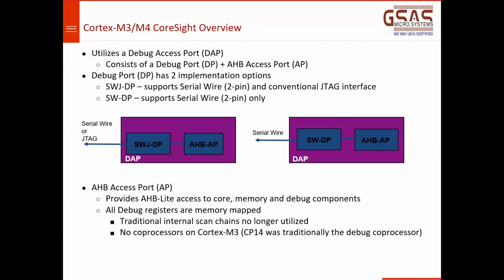And how can you access them through this access port? Using this AHB-Lite bus, which is again connected to the AHB bus. So DAP, of course, consists of a debug port plus an AHB access port.